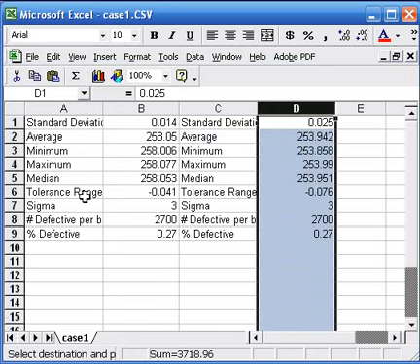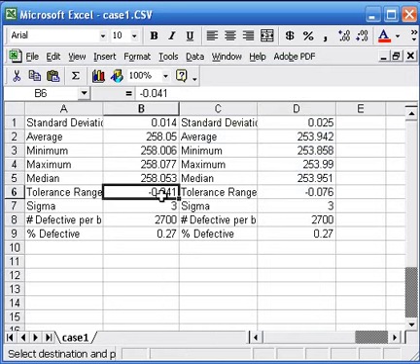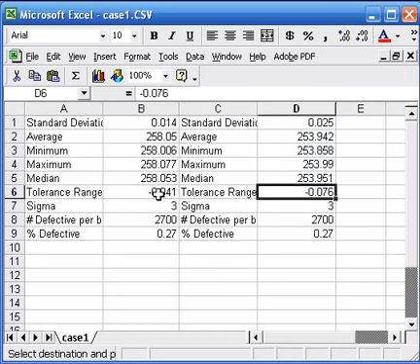So notice the tolerance range, which is the sum of the tolerances, and is changing as the mechanism position is changing. So like this, we can quickly do a lot of measurements, maybe whatever you wish, because the process is pretty fast. You can look at the mechanism in 10 different configurations and save the results, and then you can make an informed decision on how much tolerance to allocate to that point so that it will work within